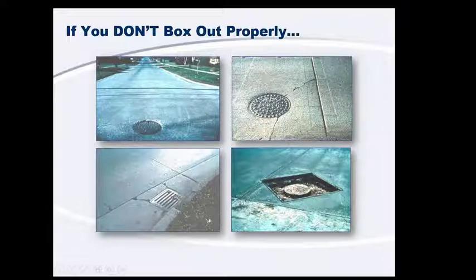And so this doesn't have a clear way to do that. So when you're thinking about joint layout, think about how your slab is going to contract to the centroid of your slab. Then you can look at the edges and where your issues are going to be. You can see here they could have easily adjusted this joint over to the inlet, and also probably added an isolation joint around it. Here could have adjusted this a few different ways and not ended up with a few triangular slabs and an interior edge that's just going to become an issue as well.